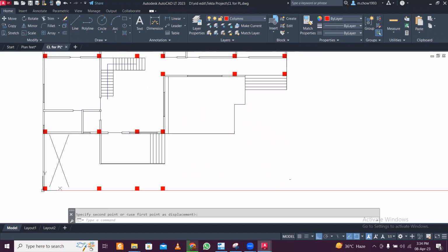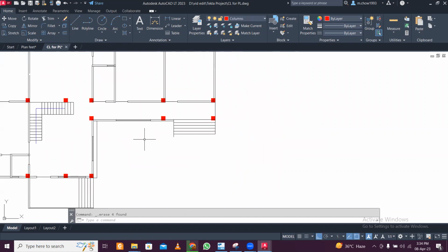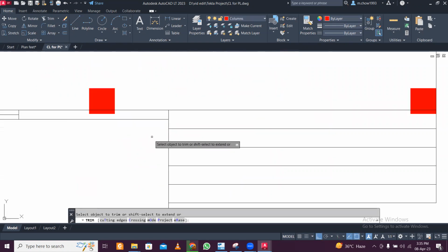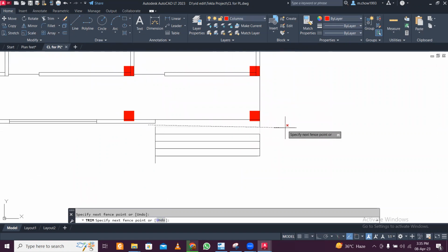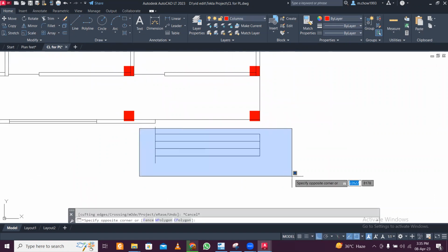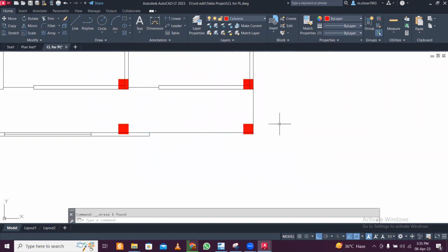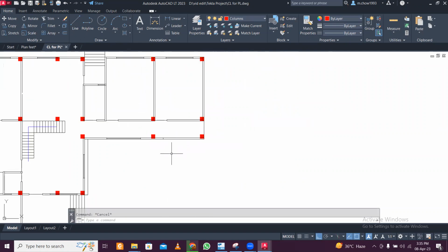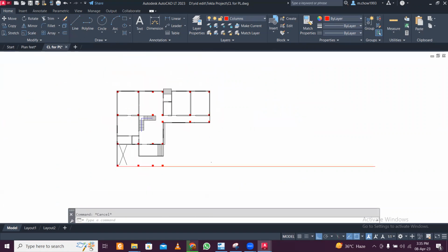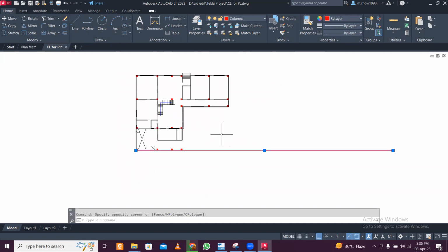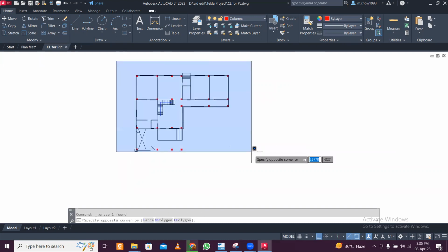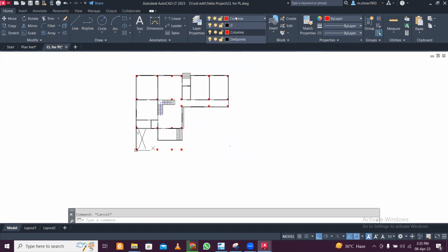and now I'm going to delete the things which are not structural parts. I don't want to confuse things within Tekla. So TR enter, and then F enter. So yeah, this is done. And then you can delete this now, and select this. We have two layers, right?